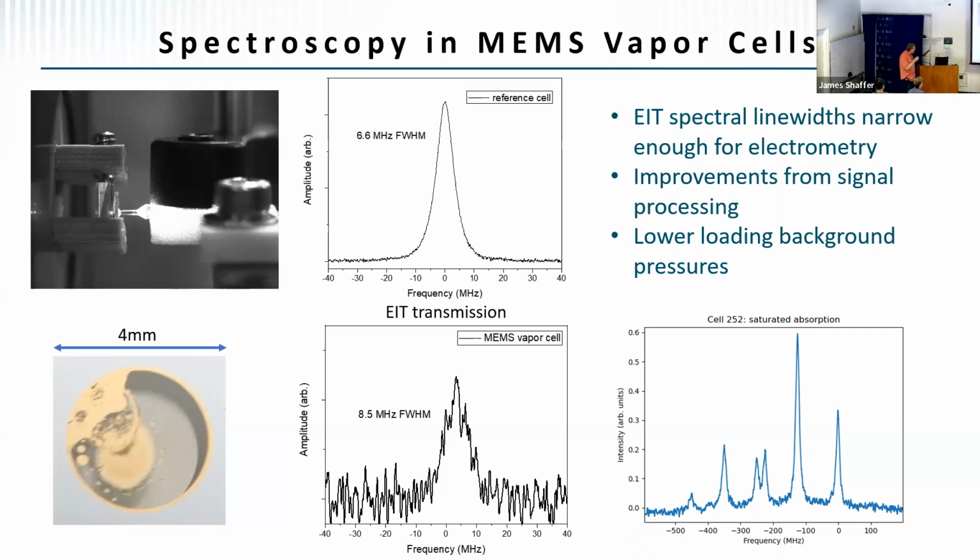So we also need to fit fiber onto these cells to fiber couple them, and that's a little bit challenging. There is science that goes in there as well, because there are several different pieces of fiber that couple light in, because we transport very different colors of light to the vapor cell. In order not to get too much attenuation, we have to splice the fiber near to the cell so that the fiber where we have a compromise in attenuation is not long.